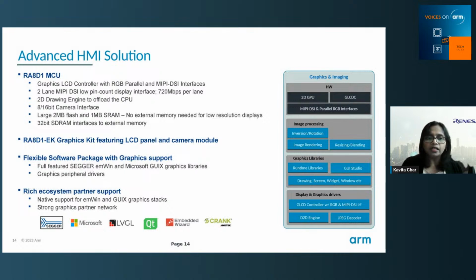The 2 megabyte flash as well as the 1 megabyte SRAM allows customers to support low resolution displays without any external memory. For the resolutions that require large memory spaces for storage of their frame buffers, we have included a 32-bit SDRAM interface to this external memory.